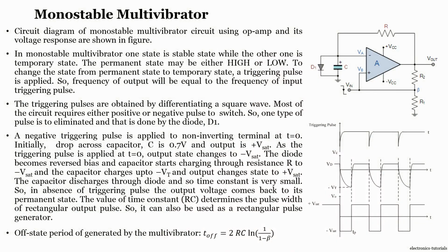So, as the professor discussed in the module, I may not go deep into the complete explanation of the circuit. Now, when we go to the monostable multivibrator, this is how the design looks. If you compare, we can see that the monostable multivibrator and the astable multivibrator look similar, isn't it? And even for monostable as well as astable multivibrator, the design uses positive feedback, isn't it? Even our previous circuit has positive feedback.